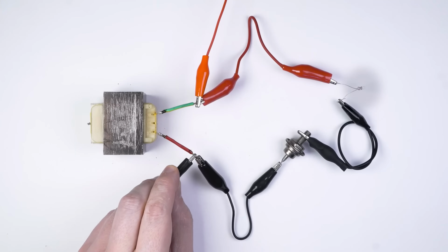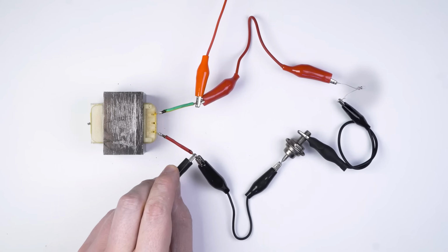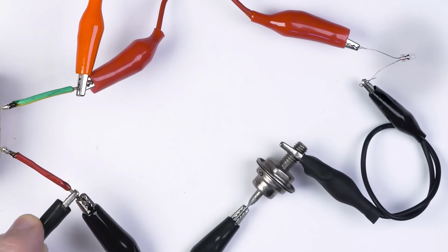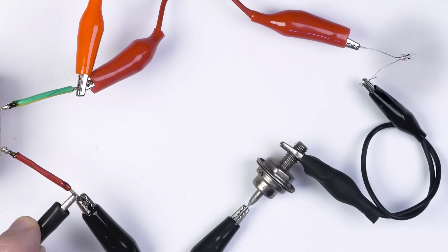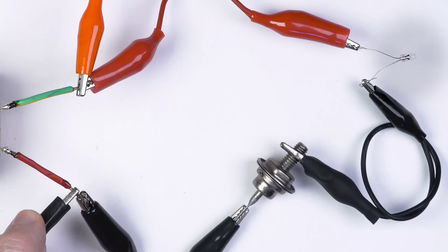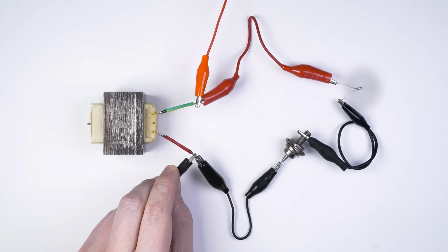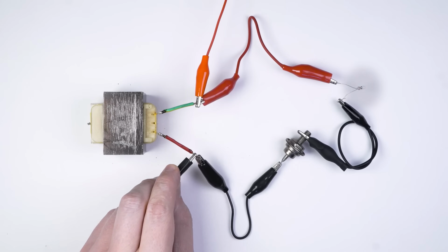Now let us modify the circuit a bit. It is known that the voltage spike that occurs on inductor's terminals, again unlike in a capacitor, has a reverse polarity. So, if we connect a diode in series with the bulb, we will have a chance to observe the process of choke discharging separately. Now the bulb flashes only when the power is turned off.